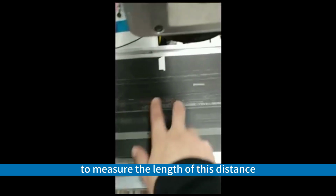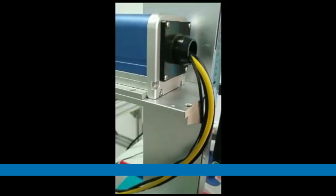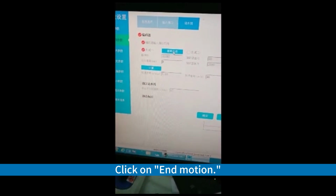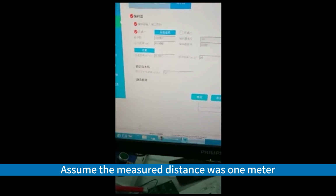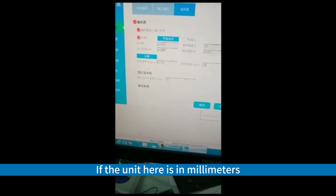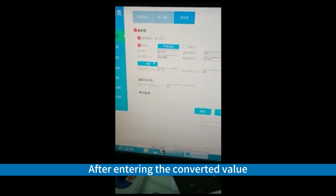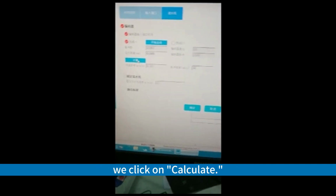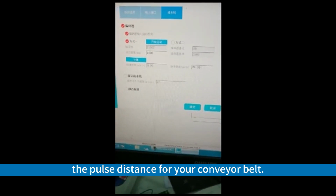and take a ruler to measure the length of this distance, click on End Motion and enter the measured value. Assume the measured distance was 1 meter. If the unit here is in millimeters, we need to convert 1 meter to millimeters. After entering the converted value, we click on Calculate. It will calculate the pulse distance for your conveyor belt.